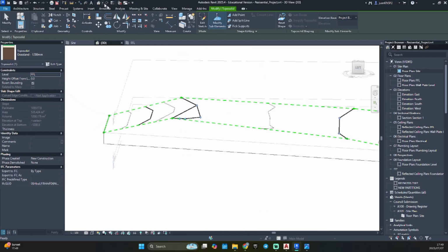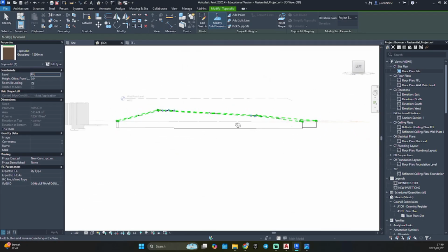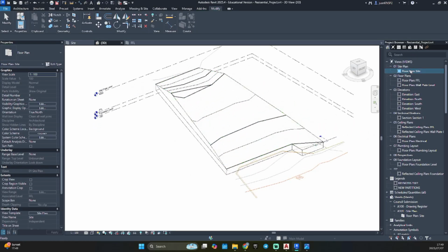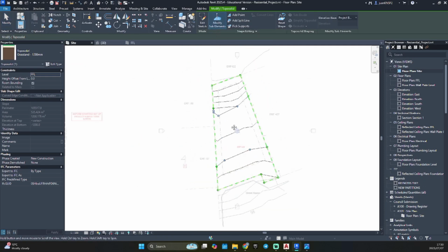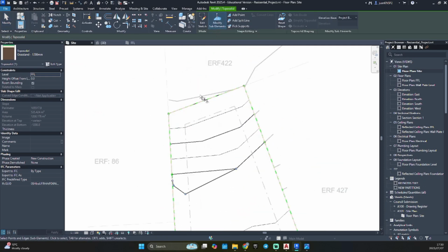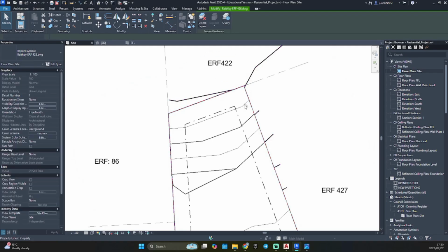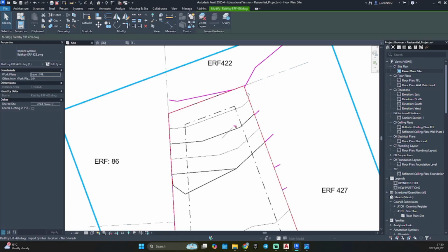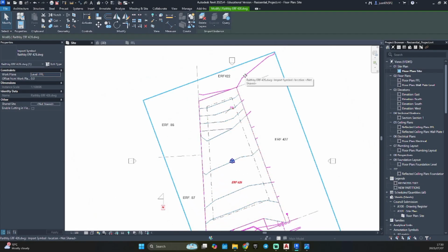Go back to 3D view. There, our site has been taking nicely shape. Let's go Modify Sub Elements again, because now we need to do the back of our site, because there are contours going up. So these contours lying there and there, we need to add our elevation to them.